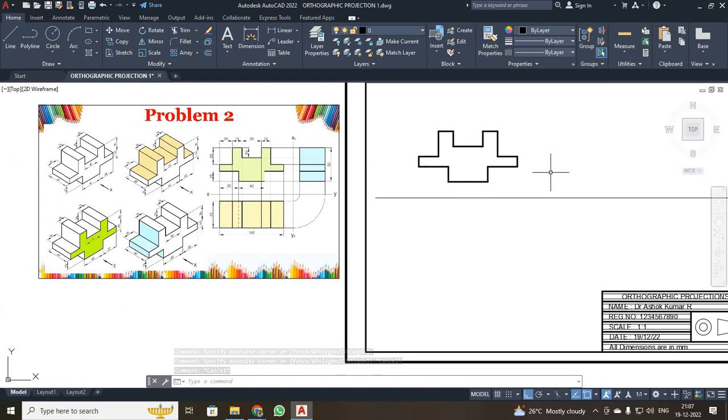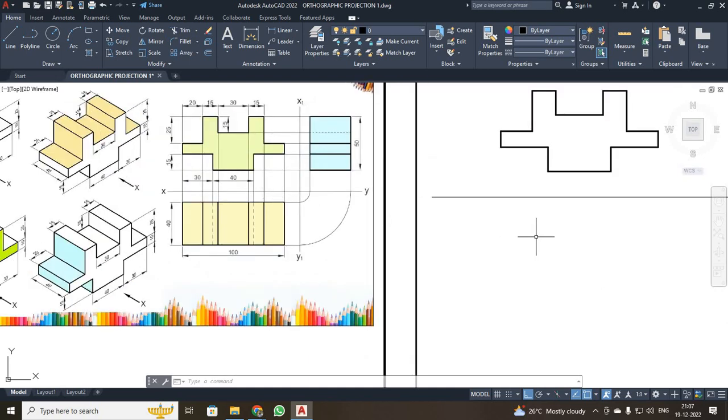Initially, when we are drawing manually, we draw construction lines. Here we are not going to draw any construction line. Instead of that we are going to track projection lines. So once again I am going to click your line. I placed a point, I have not made any click, students, I just placed a point. I moved in your downward direction, so you can see a green construction line which is moving perpendicularly towards your point. So I made a point over here, then I moved to your horizontal direction, placed your mouse over here and drew it, so that I will be getting a construction line.